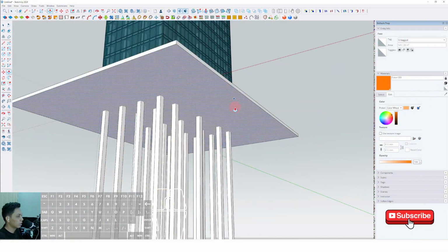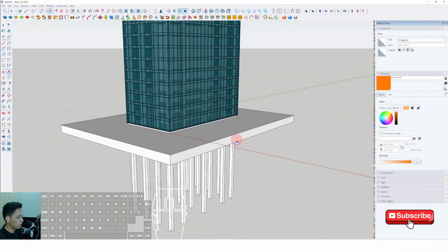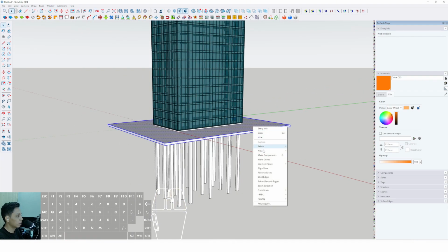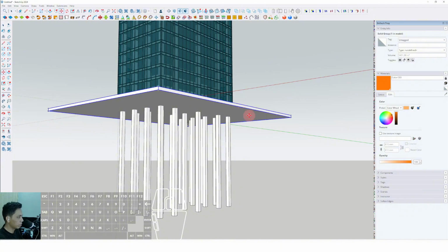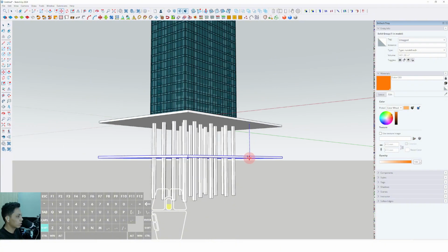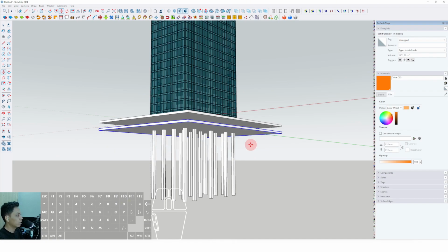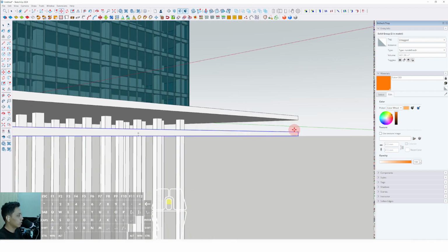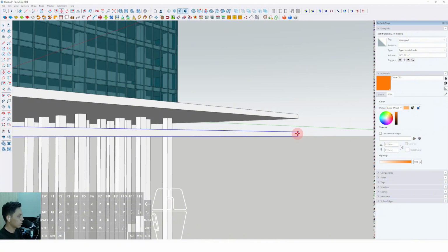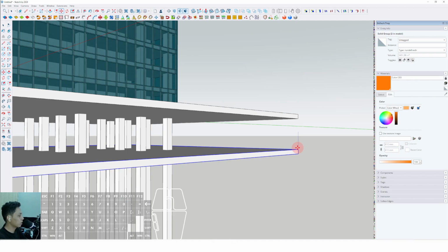Okay, then we have to push it down around 1 meter approximately, and triple click, make group, and select move, press Ctrl, place it to another position. We can type around 4 meter. Then, sorry, we have to set the distance between the floor and ceiling at around 4 meter, so we have to push it down again around 1 meter.